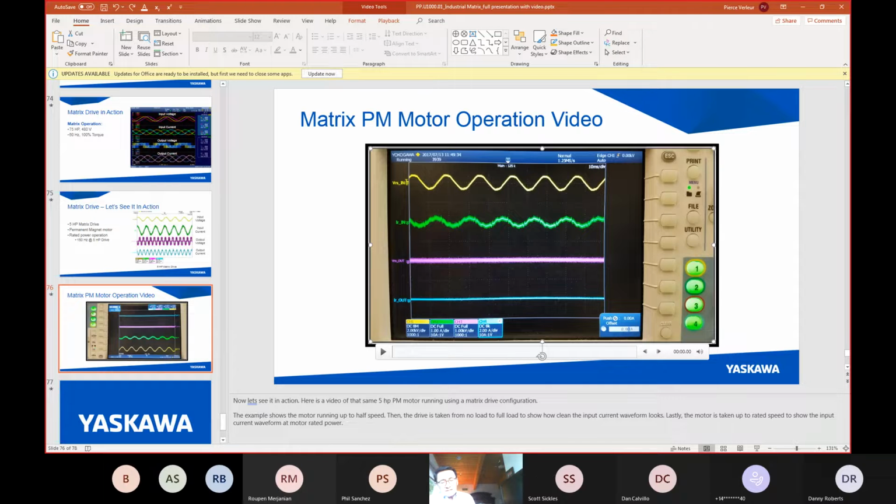And in those cases, we immediately get a foot up when we have to comply to IEEE 519, because complying to IEEE 519 for a conventional drive is going to pretty much double the cost of that drive, getting it close to the cost of the matrix drive. And now we're dealing with the input end, this green waveform on this oscilloscope. That comes with the matrix drive, and it requires you to just about double the cost on a standard drive to achieve it.